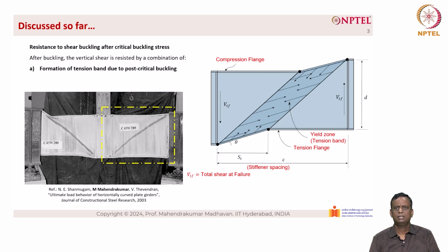Basically, it denotes the anchorage or the distance between the two plastic hinge formations at the tension flange, and then what you see at the top is S_C, which is also the anchorage point. Basically, the distance between the two plastic hinge formations at the compression flange, one at the compression flange and another at the stiffener location, is denoted as S_C.